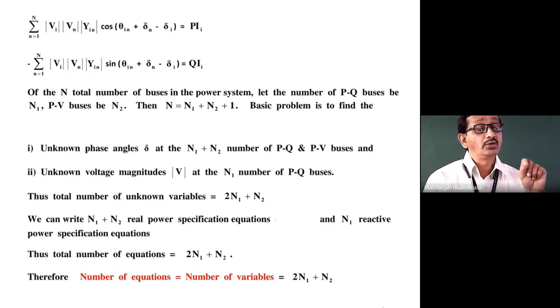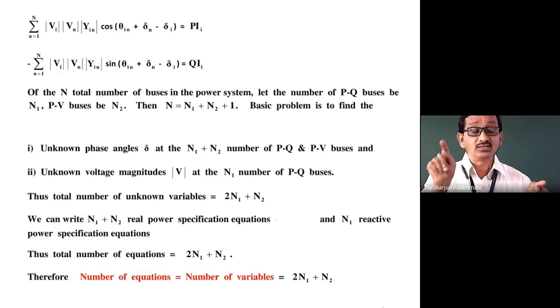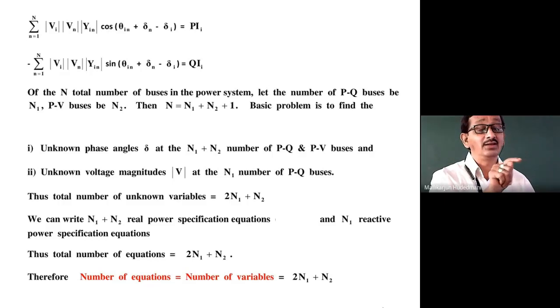Because if I solve the reactive power equation, it will connect to the voltage. If voltage is not being maintained appropriately, it is the indicator that the system has a reactive power imbalance. Hence, to address the voltage issue, I must solve the reactive power equation. Then, how many unknowns are there for me in the N bus system of a problem? Only load bus voltages are not known.